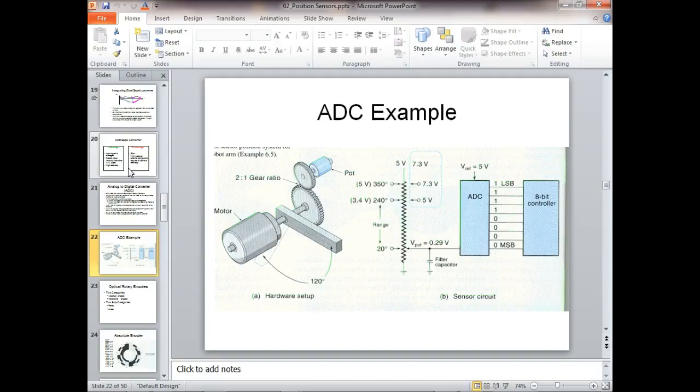What does the potentiometer give us that represents position? Well, we can't deal with degrees because my PLCs don't understand degrees. An analog sensor has to give us one of two things to represent whatever it represents: a voltage or a current, right? You understand? And a potentiometer is going to give us a voltage. So we bring a voltage in.